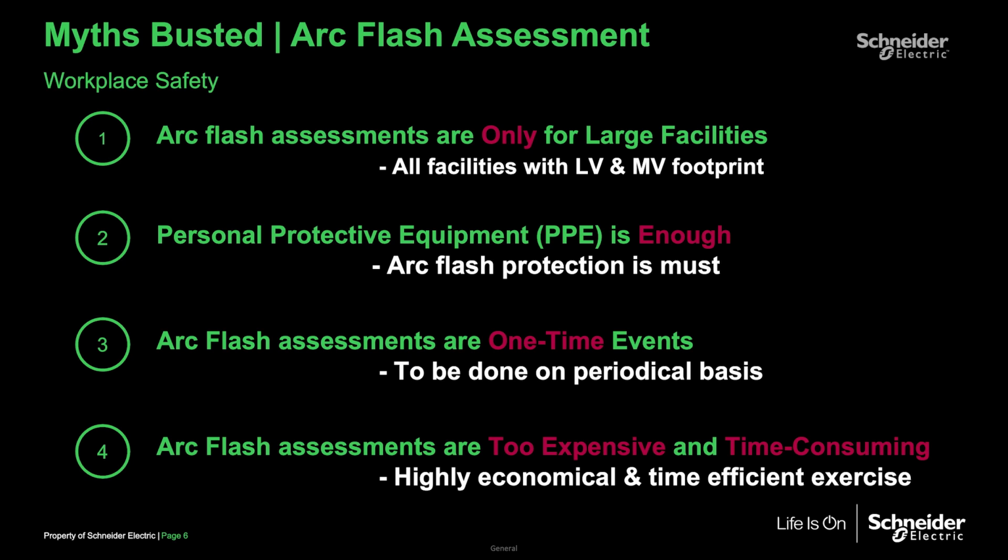Second one, PPE is enough. PPE might be enough for COVID, but not for arc flash. I am not recommending, and I'm saying this as an OEM and a product manager of this portfolio, that yes, we recommend PPE, but that's an additional layer of safety. PPE alone is not sufficient to take care of arc flash damages.